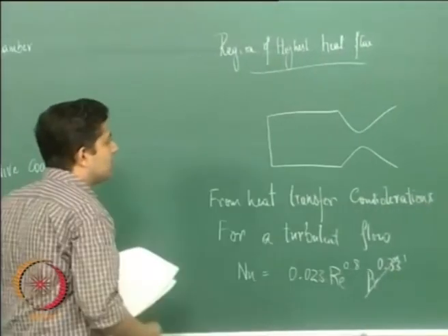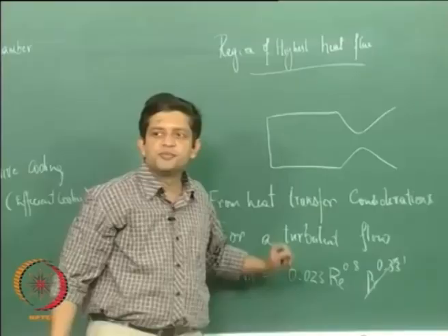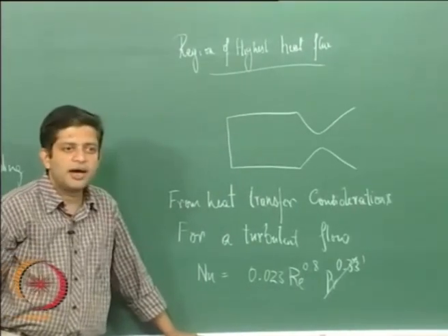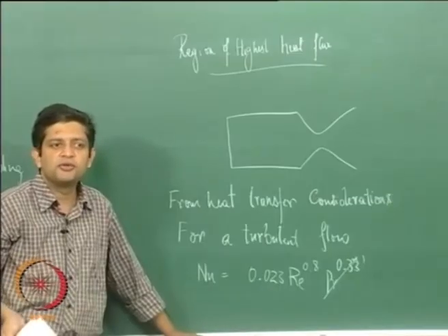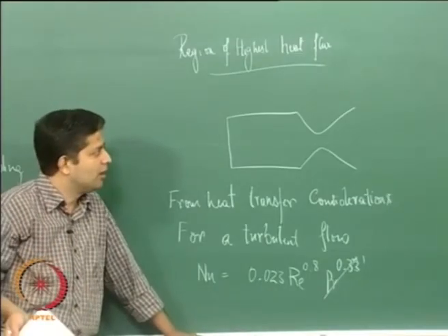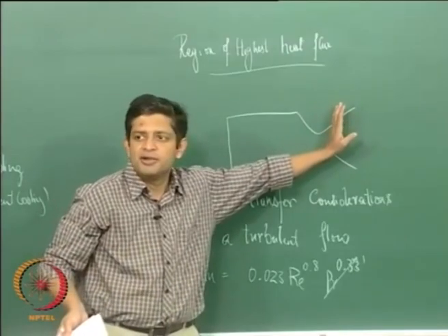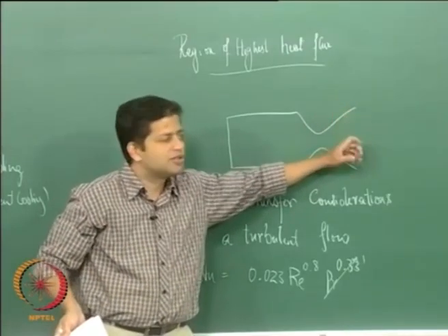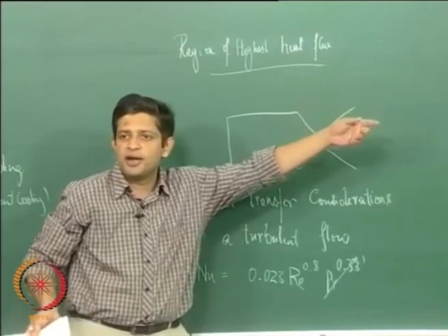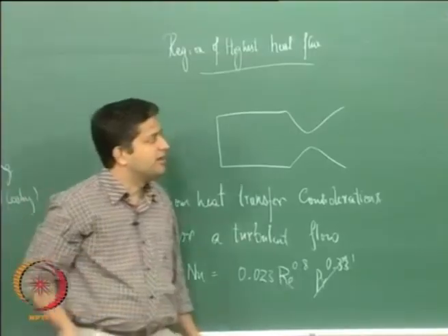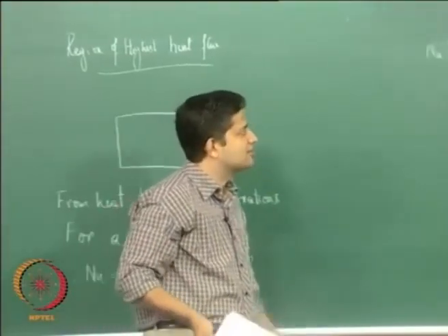The reason for expressing this in terms of mass flow rate is that if you look at the flow through a choked nozzle, which is always going to be the case in rocket motors, the mass flow rate at any section is the same, it is a constant. So it is better to write the Reynolds number in terms of m dot. We will see that we can find out certain things better.